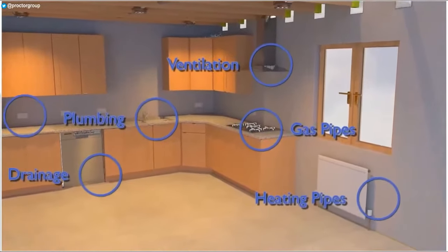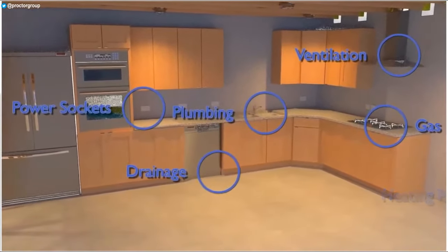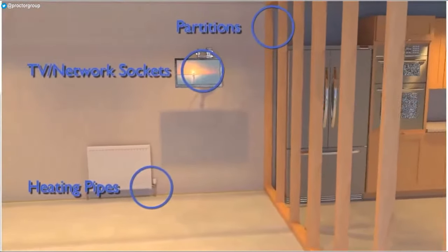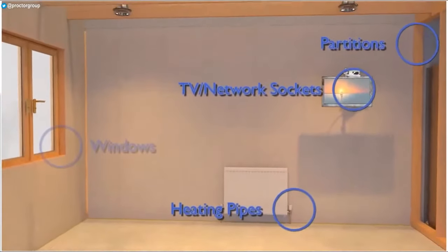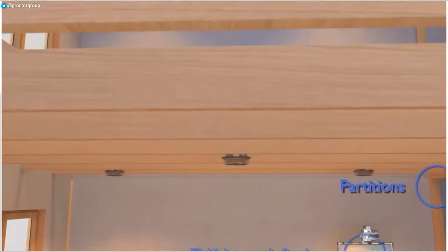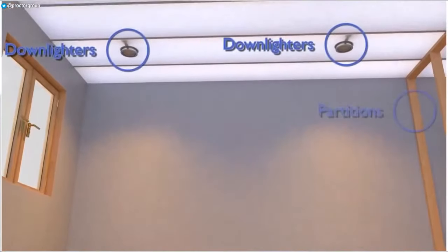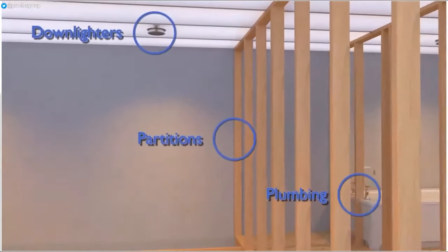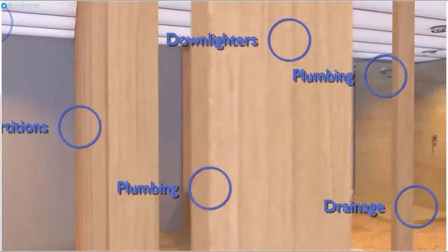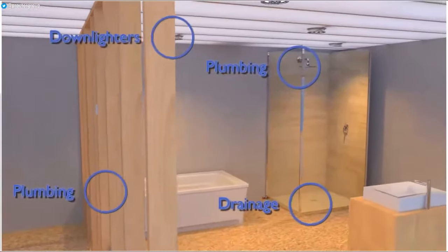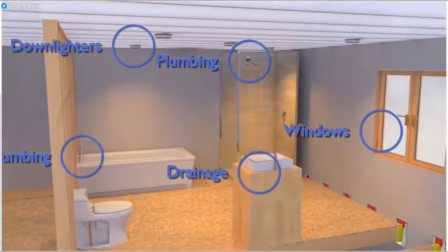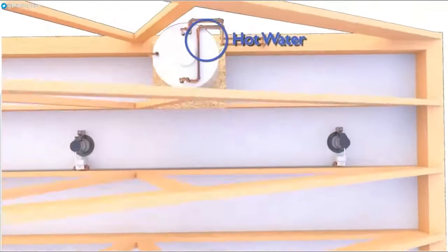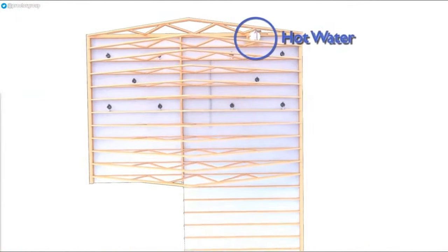Modern homes contain a huge variety of different services such as switches, sockets, and TV connections, all of which require cable runs and therefore penetrations through an internal airtight layer. This means that in addition to taking care to ensure these installations are scheduled and detailed such that penetrations through the airtight layer are minimised, specialist proprietary switch boxes and other hardware may be required. As well as potentially increasing costs, the requirement to use such hardware may lead to delays if it is not readily available for purchase. A worse outcome may be the substitution of less well-sealed components, with a corresponding reduction in performance.